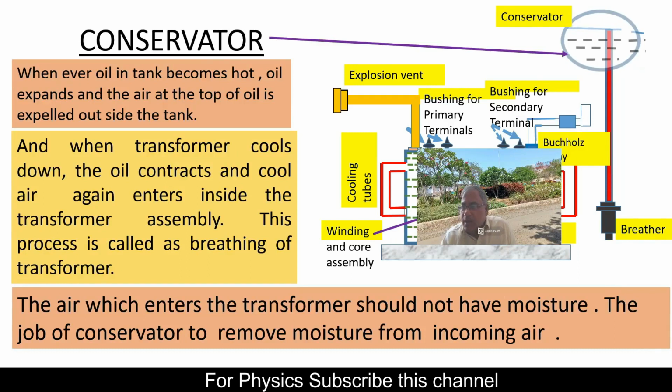Whenever the oil in the tank becomes hot, the oil expands and air at the top of the oil is expelled out of the tank. When the transformer cools down, the oil contracts and cool air again enters the transformer assembly. This process, hot air going outside and cool air coming inside the transformer, is called the breathing of the transformer. The air entering the transformer should not contain moisture. The job of the conservator is to remove the moisture from the incoming air.